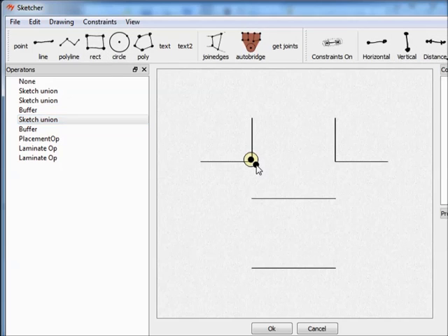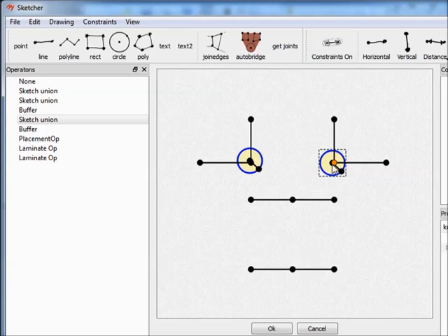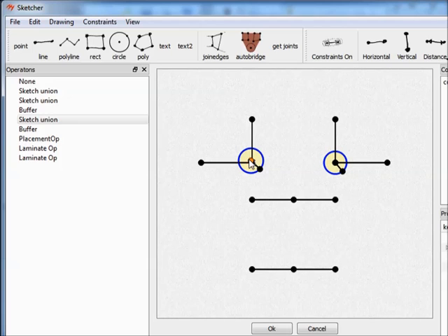There are a lot of ways to clean up hinges. This is pretty much just the simplest one. So I use the constraint toolbox to both locate the center of the hole as well as to make the radii of the circles equal, and then to define the radius of each circle.